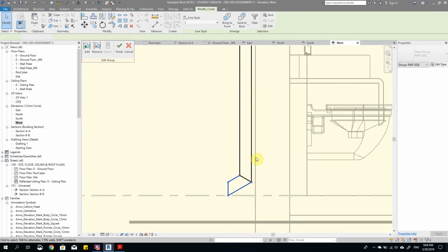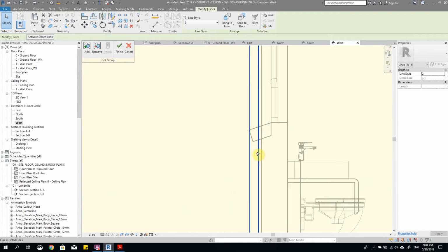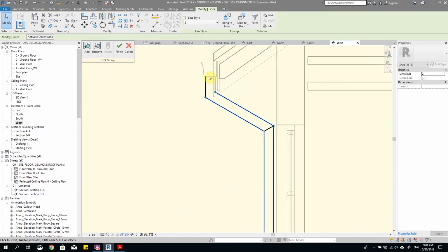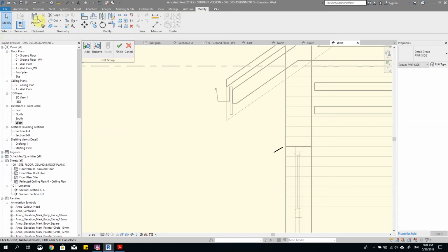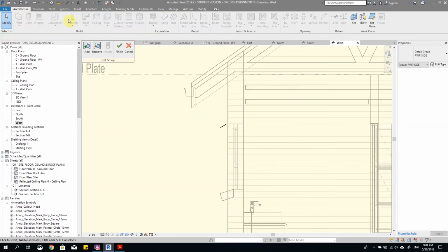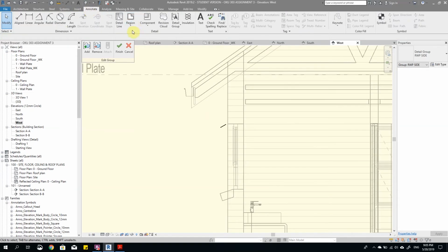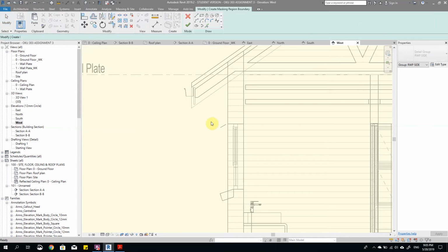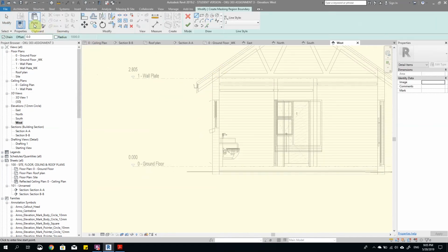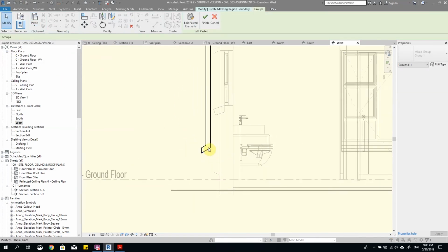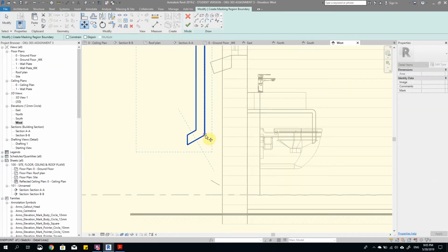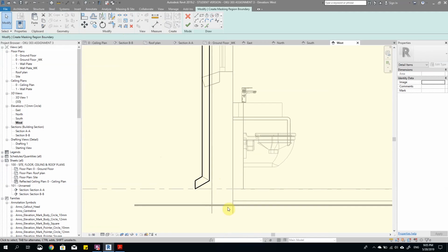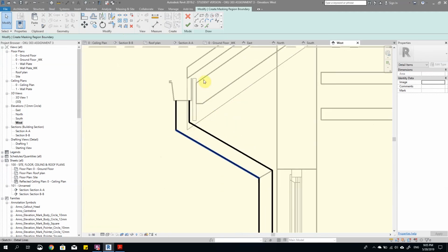So what you can do is grab this line work, just this line work, and you're going to use the cut tool, and you're going to go to architecture, annotate, mask region, start a command, and you can use the paste from clipboard, and I will move all of this, move this in line with that. Excellent.